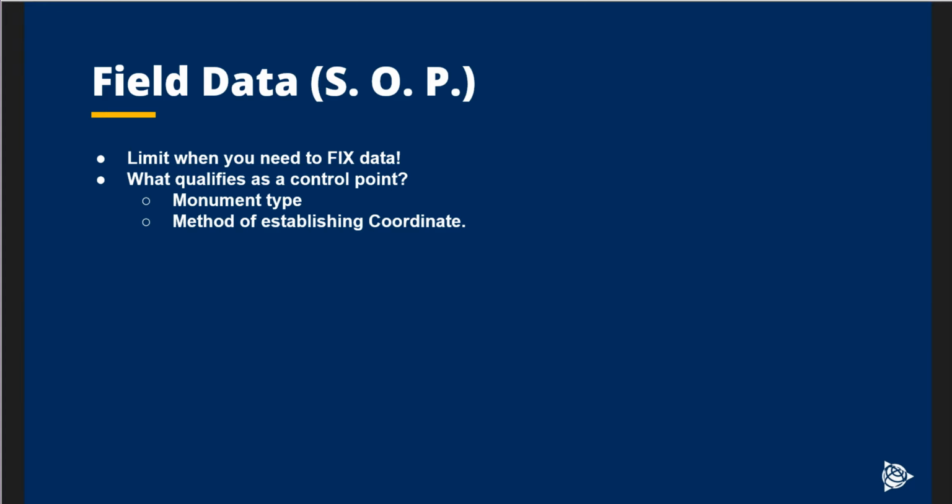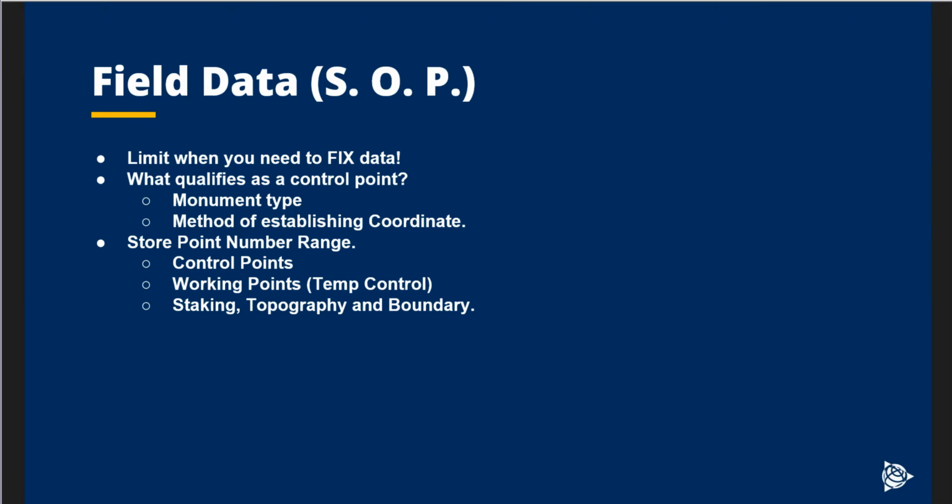When would you promote a measurement, and the value that you measure, on a monument? When does it become a control point, right? I don't think a lot of people think about that, but that's something you need to think about in your SOP. What kind of measurements, what kind of redundancy elevates a coordinate to being control quality?